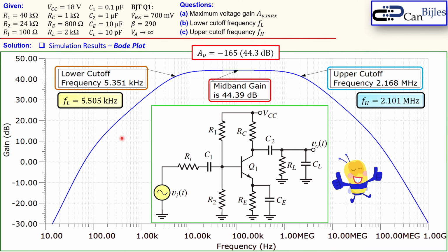So it's very nice that we see here a very complex circuit with a lot of parameters, and we managed to get the lower, upper and the midband voltage gain very close to what it actually is according to simulations. So this is the complete analysis of the BJT Common-Emitter Amplifier, in the lower, upper and the midband voltage gain, where you see a lot of details.